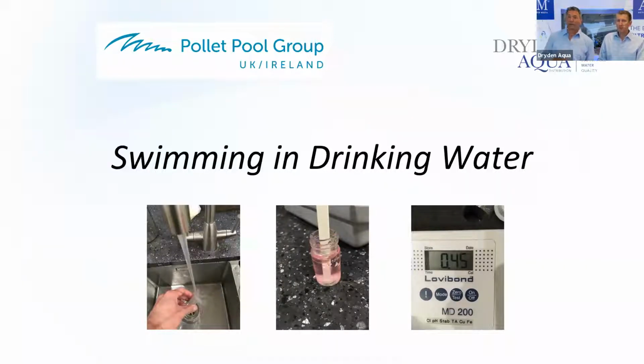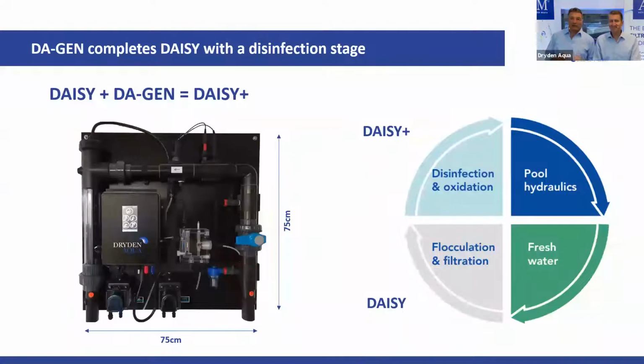It's 0.45. And if you do the same analysis, by the way, in Edinburgh, you find 0.9. Also combined chlorine, tap water can have up to 1 milligram per liter of combined chlorine. That's always a little bit of a problem for us, because the tap water is much less good than what we have in our pool water. Actually, we want to have it much better than at least this drinking water in the UK.